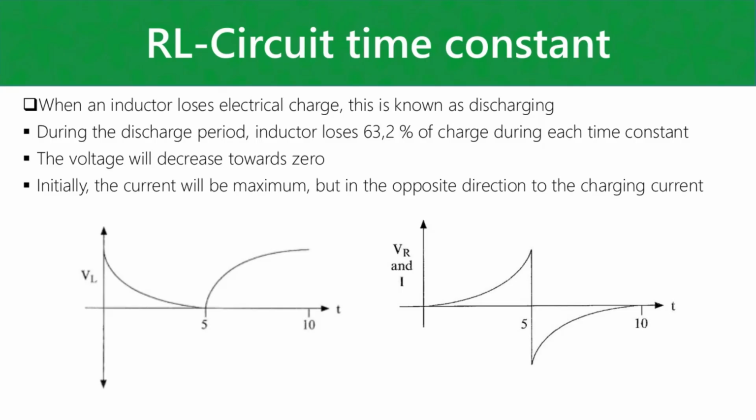Okay, and you can also discharge the inductor. There is a problem with this curve, however. This curve is wrong. Or is it this? No, sorry, that one is actually fine. This curve here, this one is wrong. Your current can't go to a maximum when there's no source. It actually needs to look something like this. Or your voltage across your inductor will look something like that.